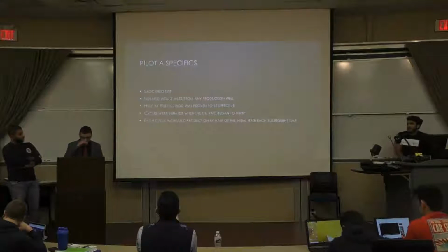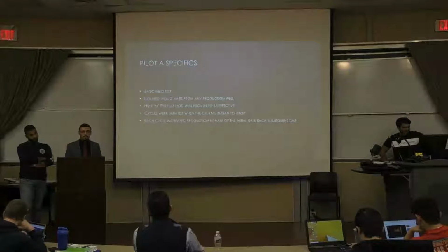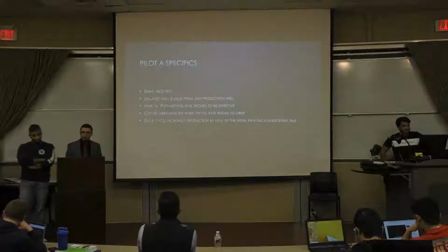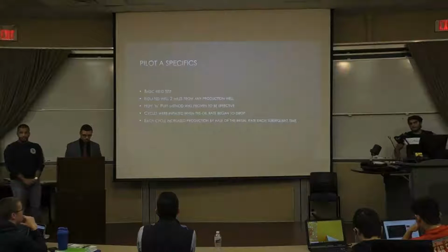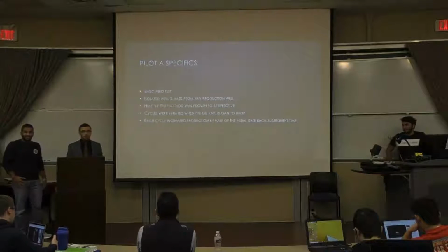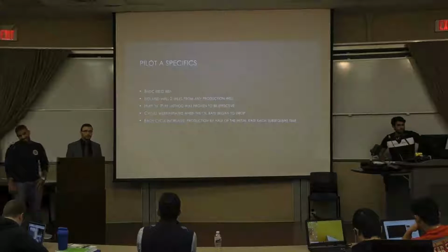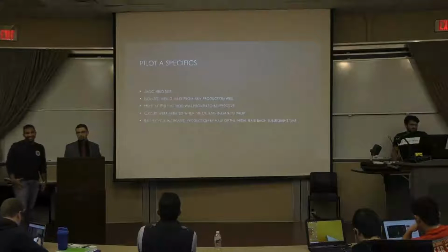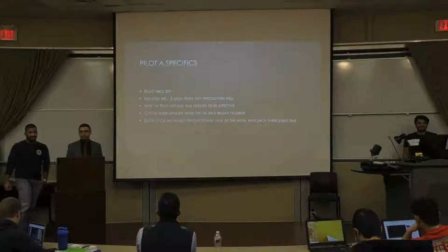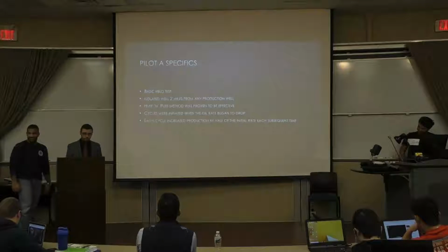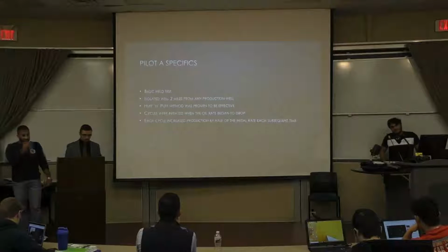So for Pilot A, it was a pretty basic field test. It was one well. It was 2 miles away from the nearest producing well, mainly to keep any gas that was injected from migrating and skewing any data or results. They used the huff and puff gas method, which we've talked about several times. They cycled gas every time the rate would drop below a certain point, and their results proved that each cycle would increase the production by half of the initial rate they had before injection.